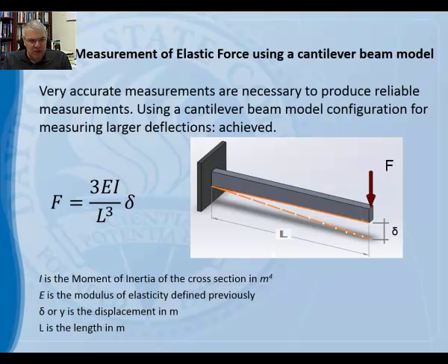Pretty much I draw a line here that is on the outer fiber of this beam. The assumption is if this line moves down by an amount of delta, you can see that every line on this, if it's a rigid prismatic bar, there'll be no deformation of the bar itself under the application of load except at the tip.